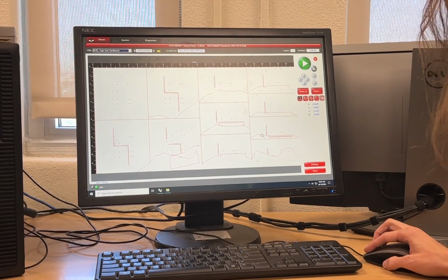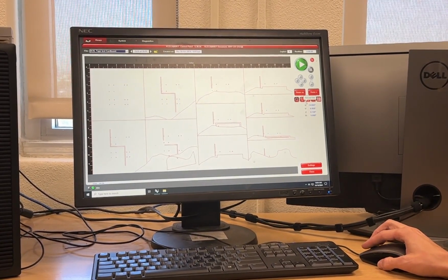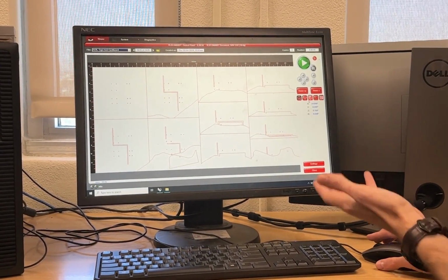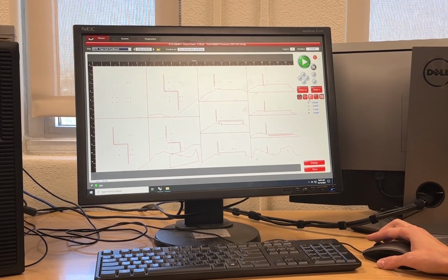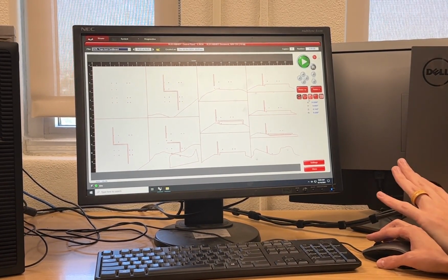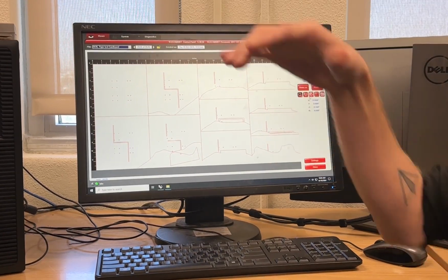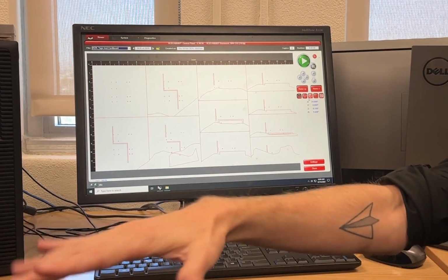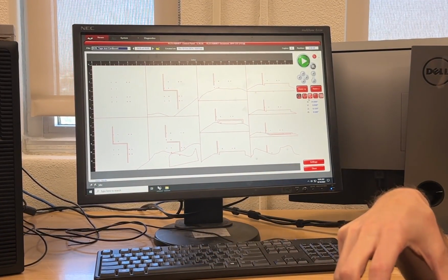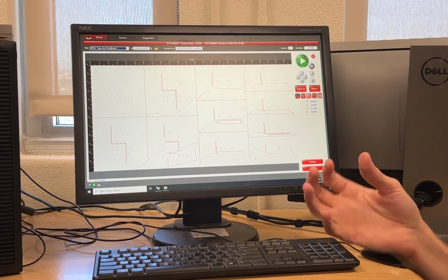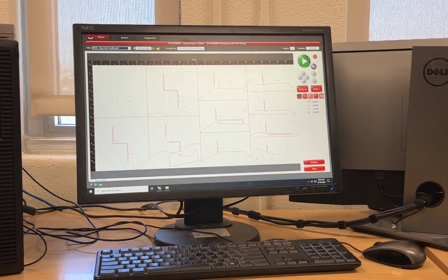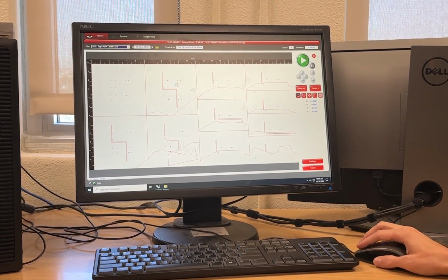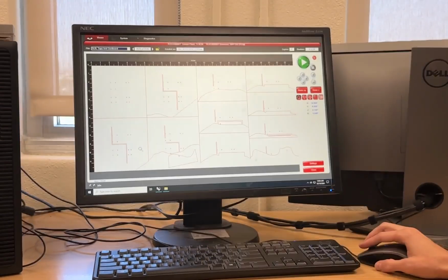And we can zoom in, zoom out. A couple of things that we can do here. For instance, right now I have a really small piece of material, right? It's not obviously gonna fit any of this, which is why I was saying I'll run it, but technically you shouldn't run the laser on the bed, right? It's a really good way to start a fire because of all the debris that might be inside, interlocked in those little honeycombs. So it's never a good idea to run this, but I'm gonna run it today because, well, I am a professional. I'm gonna stop it, of course, before anything bad happens. But hopefully we can get one of these pieces out of that sheet.